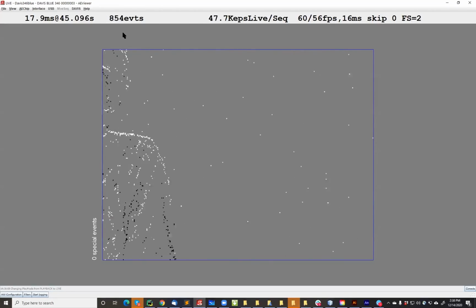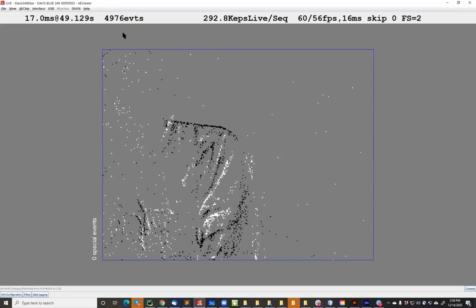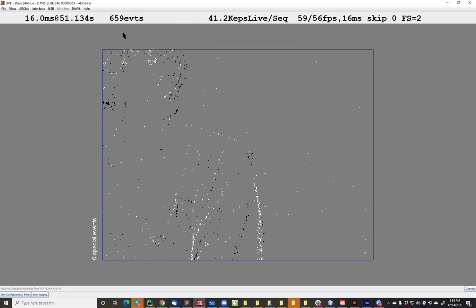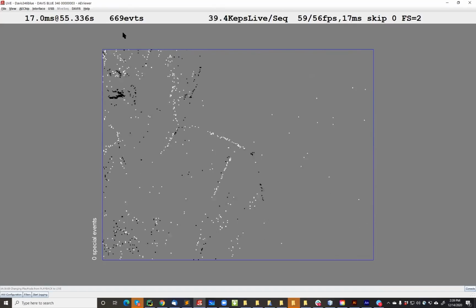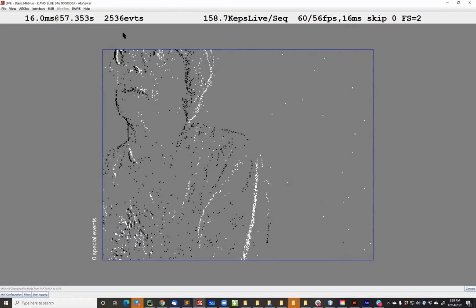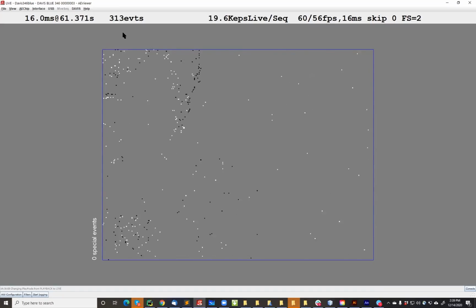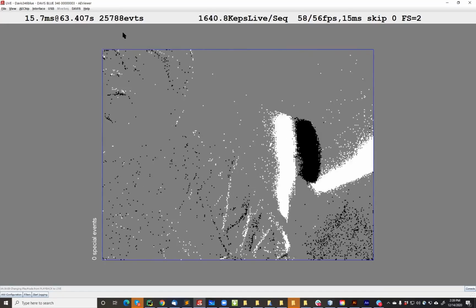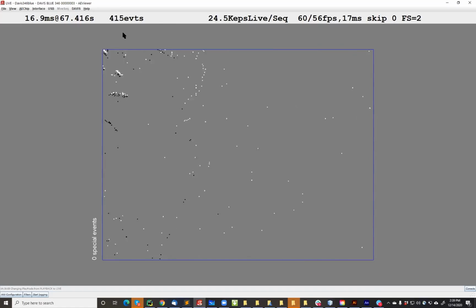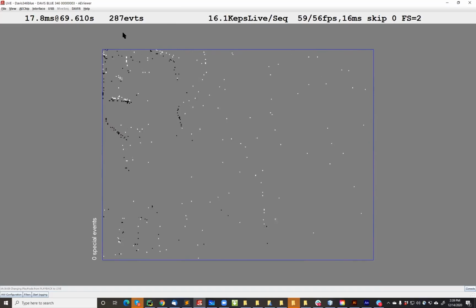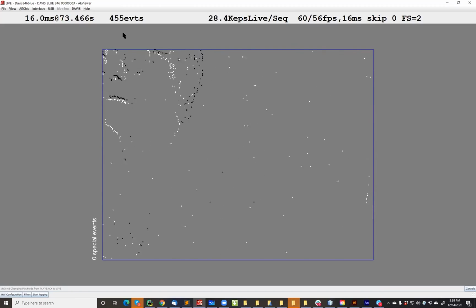In reality, are they a little bit batched because of the communications through the USB? Yeah, it's batched into packets. The packets come at a variable rate. If there's no action, the packets come once every 100 milliseconds or so, very slowly. But if you really move rapidly across it, the packets come every 1/8 of a millisecond. So 8 packets per millisecond when you're using a USB high-speed interface.